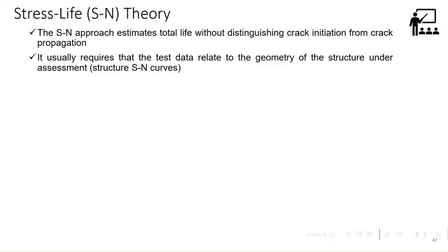But if you have an SN curve for the component available, then nothing like that is needed. You can directly use that SN curve without going through all the modification factors. If you are using an SN curve for a material, then you need to apply them. This is required to improve the accuracy in the result.